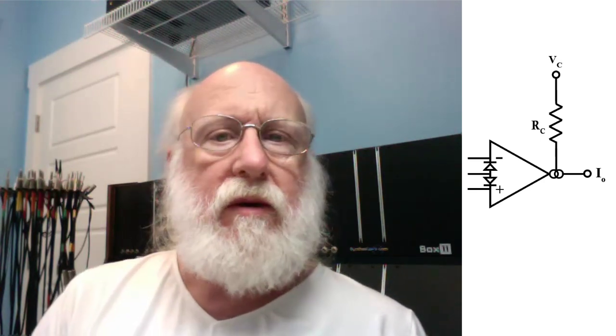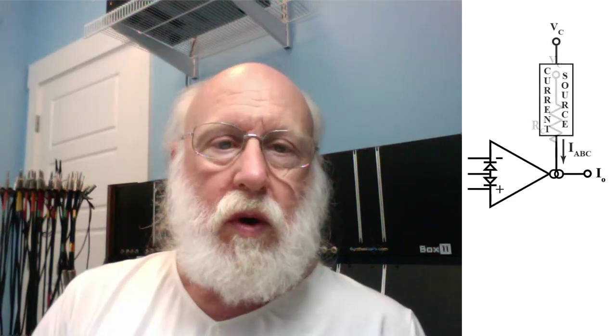In our last video, we introduced the amplifier bias current and showed that in a very simple case, we can just connect a resistor between that input and the control voltage, and that will allow us to control the gain of the OTA with the voltage. However, this has a number of problems. It lacks high accuracy, it's not particularly flexible, so in many cases we need something a little bit more robust than a simple resistor. In general, the way to do this is with a current source.